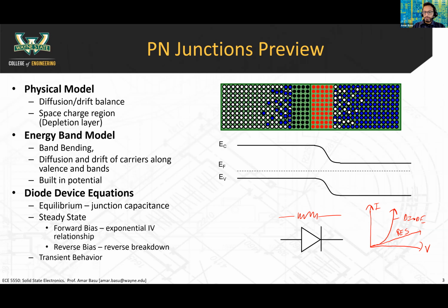When you're doing resistors, you have a linear IV characteristic, and that's useful in a lot of sensor type applications. It's useful in designing filters like RC filters, low pass and high pass filters when you combine a resistor with a capacitor, for example.